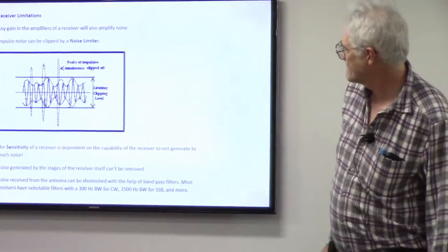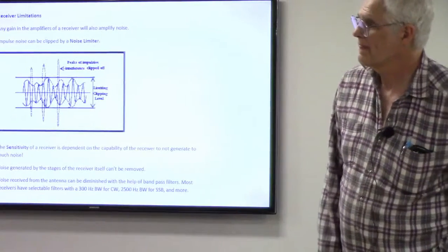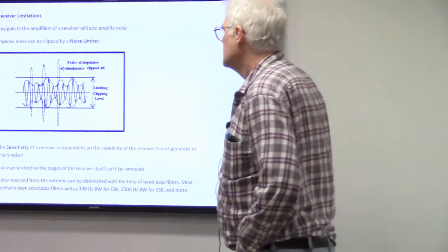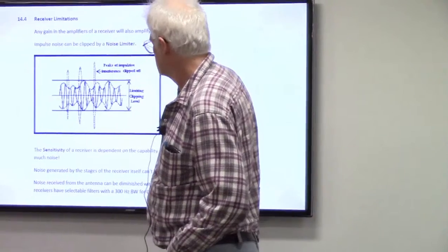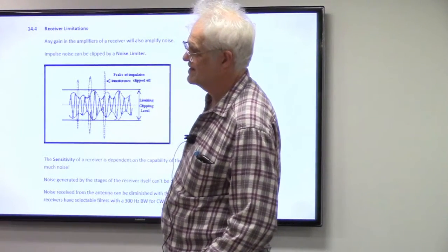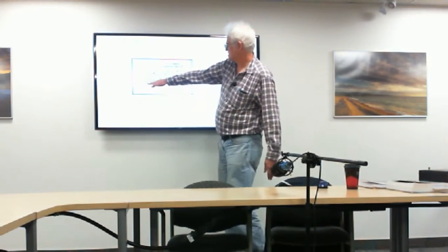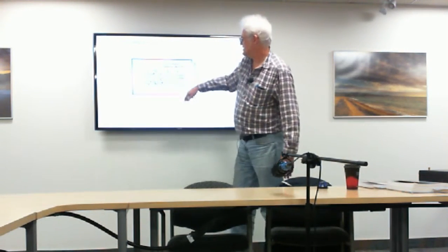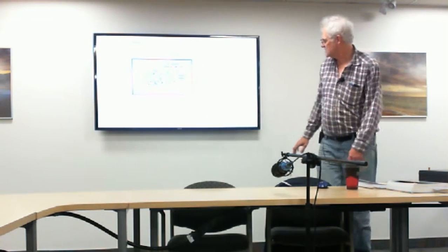But could you clip the incoming signal to the point it distorts it? Oh yeah. For example, your waveform right there, you could actually clip it lower, right? Well, if you clip it lower, you're going to start chopping off some of your data peaks. And that's the last thing you want, really.